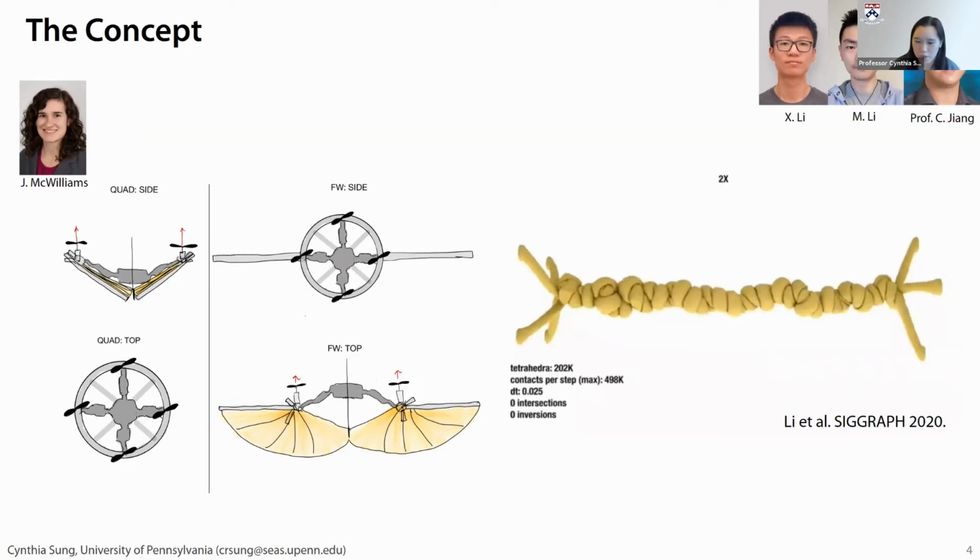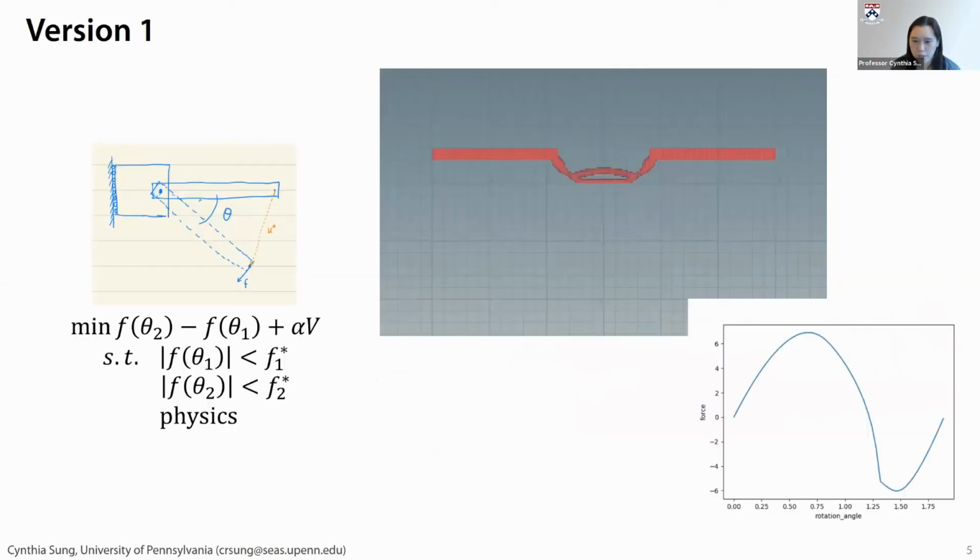And there's a lot of work out there on topology optimization. You can find a lot of papers where people look at bistable mechanisms, mechanisms that are very similar to what we were trying to achieve. So the very first step was to see whether we could design something for the middle of this vehicle so that it could switch modes. So we formulated a pretty standard topology optimization problem. What we wanted was the wings of this vehicle to snap out or in and to be driven by some material block in the middle, which we wanted the computer to design for us.